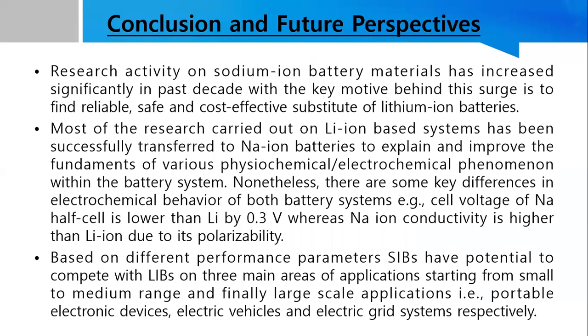Most of the research carried out on lithium-ion based systems has been successfully transferred to sodium-ion batteries to explain and improve the fundamentals of various physicochemical and electrochemical phenomena within the battery system. Nonetheless, there are some key differences in the electrochemical behavior of both battery systems. For example, the cell voltage of a sodium half cell is lower than lithium by 0.3 volts, whereas sodium ion conductivity is higher than lithium ion due to its polarizability.